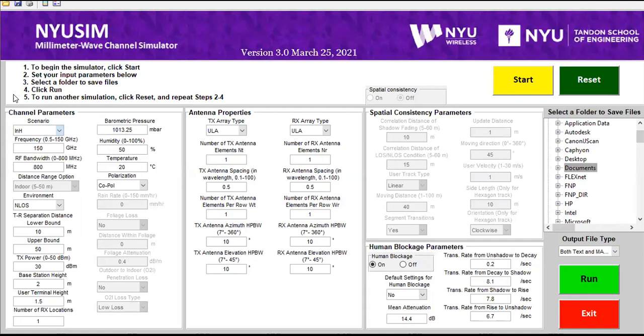What operators do in practice is they first take some particular model. If you join the radio network planning team of an operator, you'll find these things. They first pick a model, but later they tune it. They do some tests for their city, and depending on the test results, they tune the model.